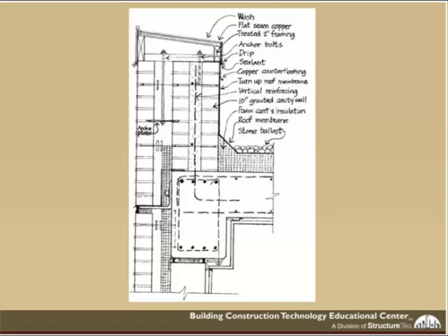At the top of a wall is actually another place. The coping, sloped coping you see up there at the top, can really be thought of as another through-wall flashing. When you look at how masonry is constructed, there's a lot of vertical stacks of brick, quite often with void spaces between them or mortar, and that leaves them very susceptible to moisture intrusion. So it's critical to get a dependable, long-lasting water seal over the top, and that's what that coping flashing does for you there. Okay.